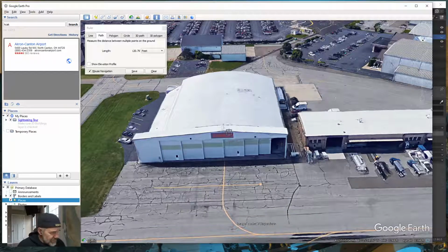So to get the center, because the center of our roof is based on this end of the door and this end of the door, plus that 1.5. All right. So we're going to take the 144 feet and subtract the 22.5 feet. And that's going to give us 121.5 feet from here to here.